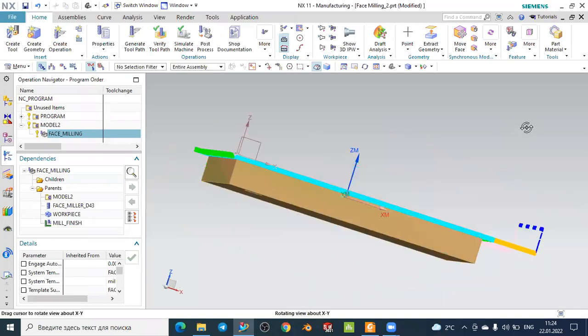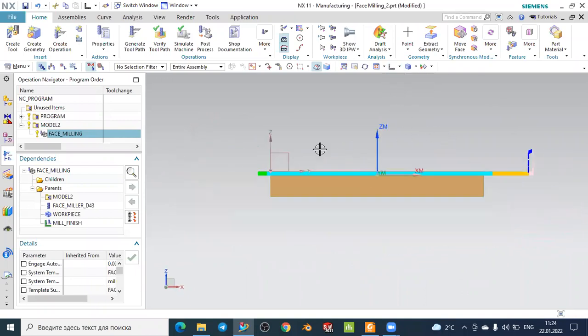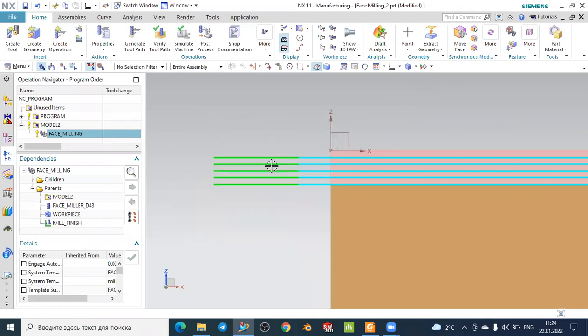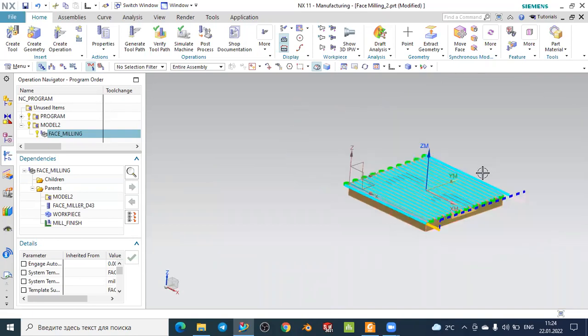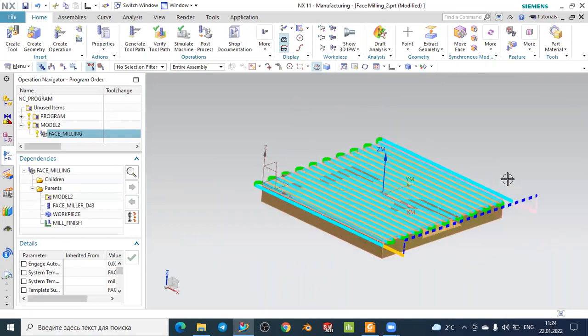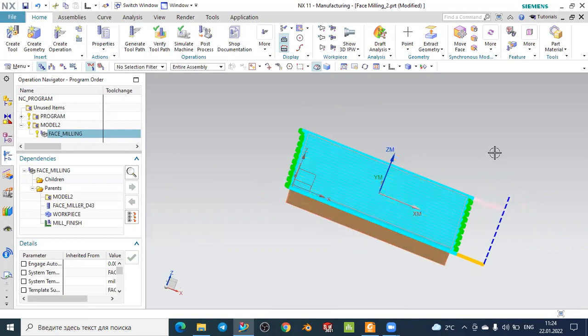We removed 5 millimeters of the surface from the top surface of this element with 5 layers. Each one was 1 millimeter, so this overstock was 5 millimeters, and we removed it. It is called the face milling operation, and we discussed the tool pass, the rapid movement, step over, the cutting operations, and so on. So now